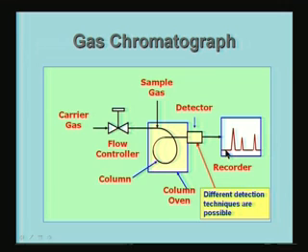So, you see that what you are seeing here is a chromatogram. This is called a chromatogram. The axis here is time, and what you see here is the concentration of the gases, the one which came first, the one which came next, the one which came subsequently, and so on. So, they are separated as peaks here. The area under each peak will be proportional to the concentration of the gas in the sample. Okay. Let us look at some of the details.